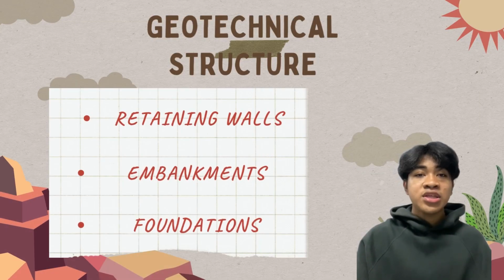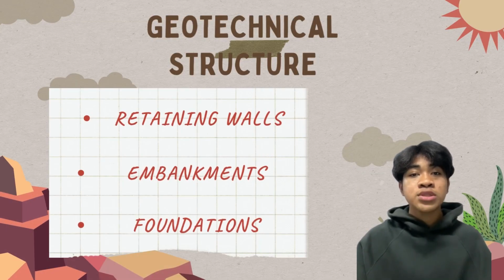Saturated soils affect key geotechnical structures like retaining walls, embankments, and foundations. For retaining walls, water increases lateral pressure, which can lead to failure if there's no proper drainage. Next, embankments, used in roads and railways, may collapse or settle when the soil underneath is saturated. That's why drainage and reinforcement are important.